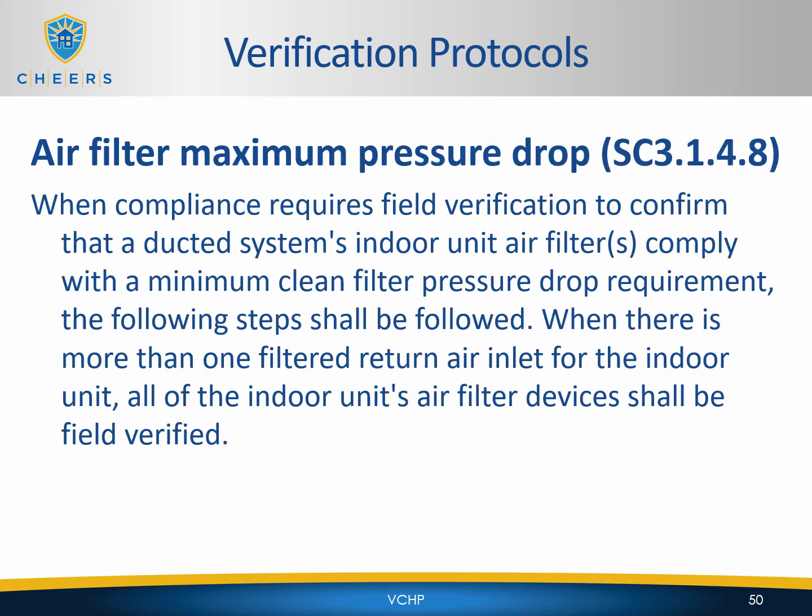Air filter maximum pressure drop. This is found in SC 3148. When compliance requires field verification to confirm that a ducted system's indoor unit air filters comply with a minimum clean filter pressure drop requirement, the following steps shall be followed. When there is more than one filtered return air inlet for the indoor unit, all of the indoor unit's air filter devices shall be field verified.